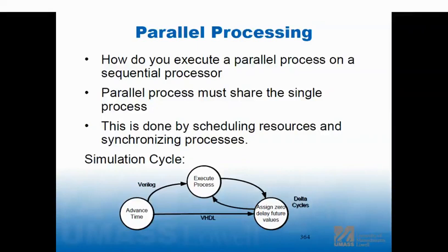Now, generally, I take that RTL and I send it to a back-end designer, and they make a macro for me with a bunch of inverters, and they send me a delay file. But every once in a while, a mistake gets made, and the RTL gets put into the simulation instead of the macro. Because we needed the RTL for synthesis, but the macro has to be in there for simulation.